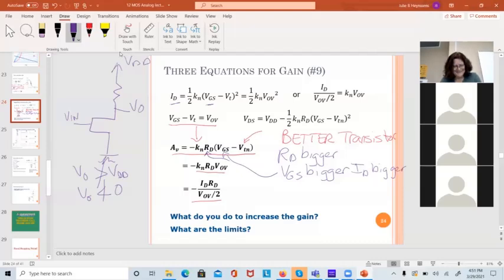Unfortunately. And the other thing is I have to keep the transistor in saturation. So I've got a few more constraints in there, and we'll talk about those much more in 380. The sad part is when the transistor goes out of saturation, it stops amplifying. You know what engineers call that? When you hit the rails because you're no longer in saturation, your circuit stops working. Unfortunately, we call it saturation.